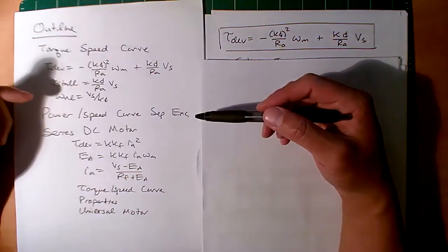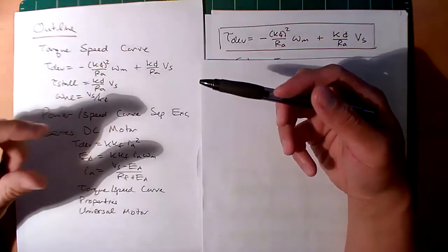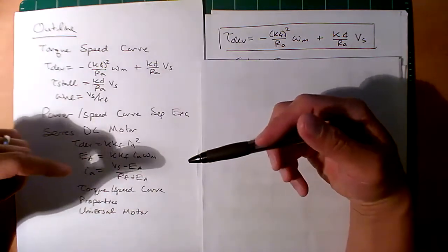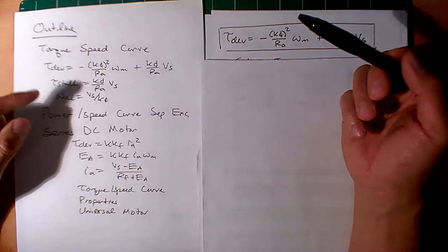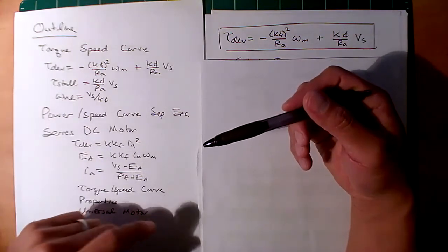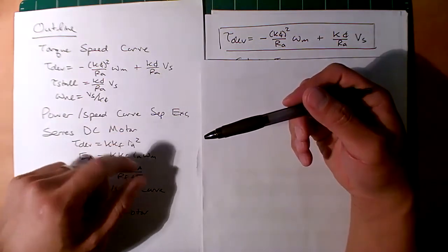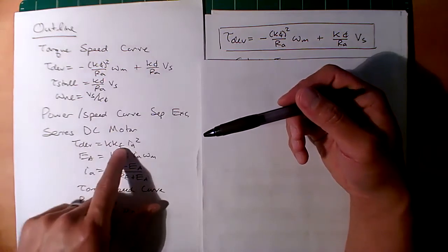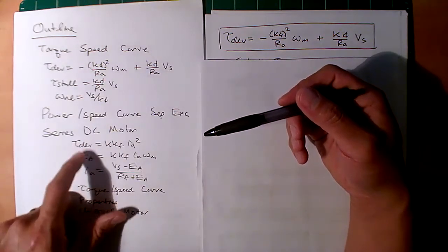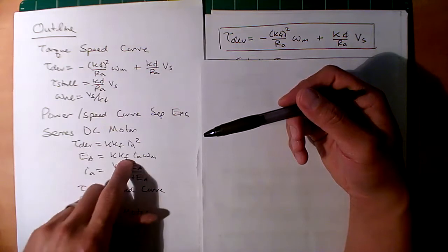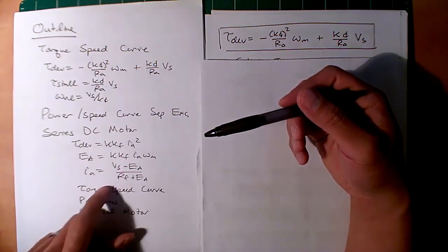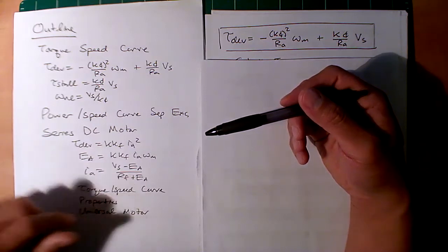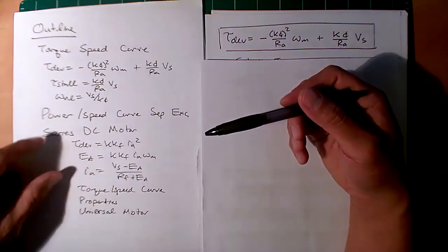In a series DC motor, the field current is now created by the same voltage source as the source for the armature, and it'll be run in series. The biggest thing that happens is that the flux is created by Ia. So notice in your Biot-Savart law, the Lorentz force equation, and your back EMF equation, there's no more phi in here. It's dependent on Ia from Ampere's law. Then this is your nodal Ohm's law. So these are the three summary equations for the series motor.